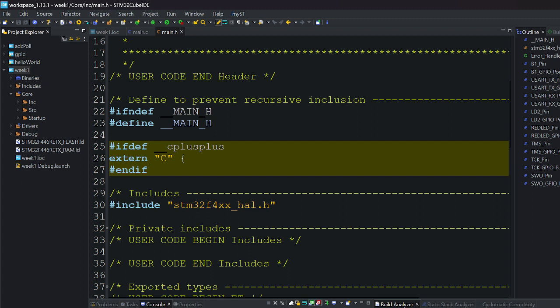By having these preprocessor directives in your header files, it means that if you needed main.h in multiple places, whichever one was called first says I exist, and it defines __MAIN_H. Then when it needs it in another file, you say include main.h somewhere else. If it exists already, it doesn't bring it in again. If you just said, I just want a .h file and I don't want any of this stuff, you can come up with multiply defined definitions or variables, because you had main.h in more than one file. In this case, it doesn't matter which one was brought in first. It says there's this tag called __MAIN_H, and that's defined. So if you see main.h in another file, we're already defined. You don't get multiply defined things.